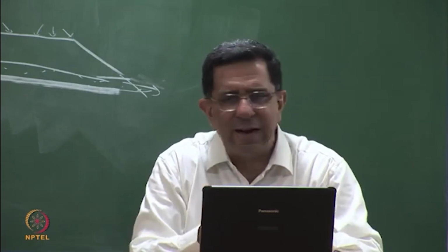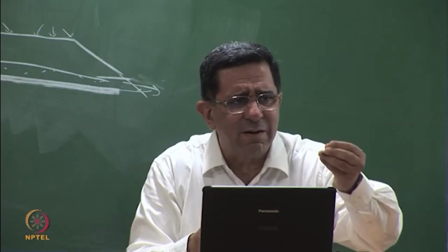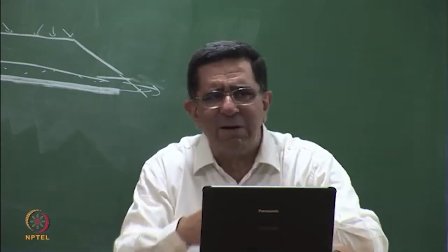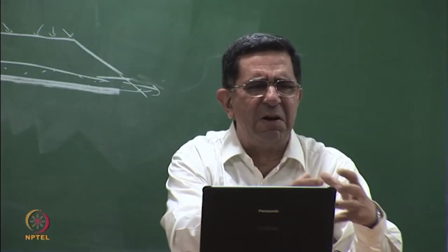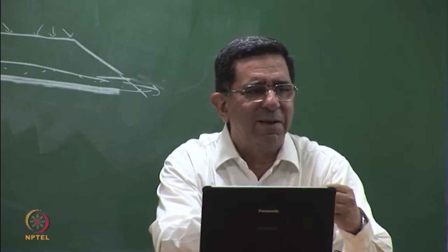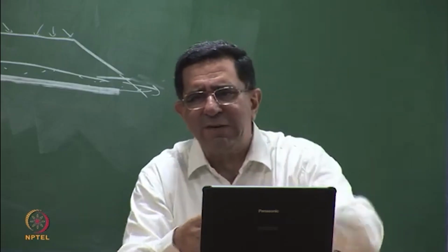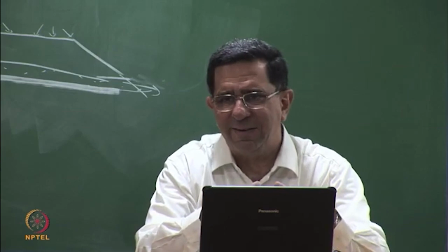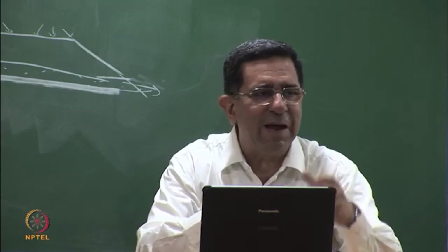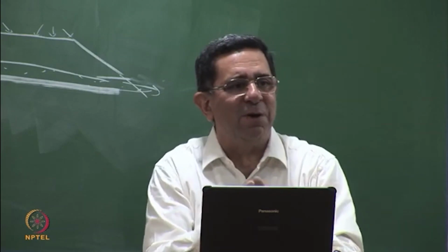I can make a hole, take some quick fix, Fevikwik, and inject it into the ground, and my whole soil will become very hard like rock. The point is, if you try to inject it, it's not going to go into the soil. Grouting only takes place in gravels and sands. It doesn't take place beyond that.